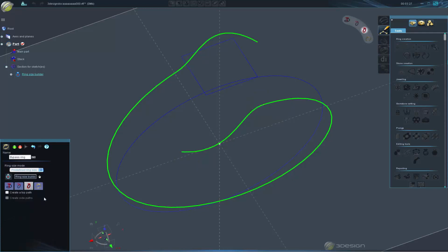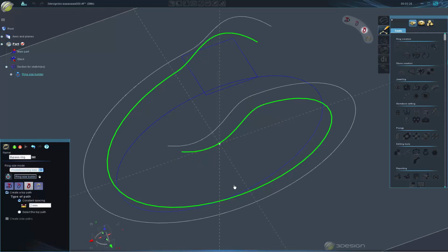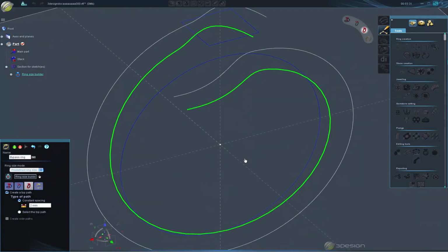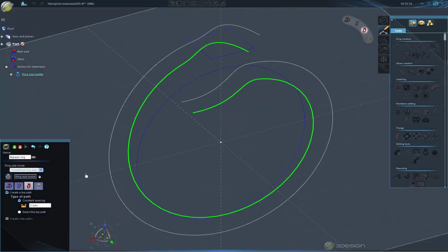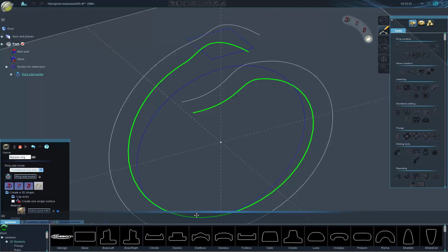You can do multiple curve sweeps with bending. You can do a 2-rail sweep. This will keep your profiles from flipping over as you're going around the bends. If you're doing a standard, you can do a 3-rail sweep. And finally, we can add a section by clicking on Create 3D Shape. This will allow me to go into my library or use a drawn curve.